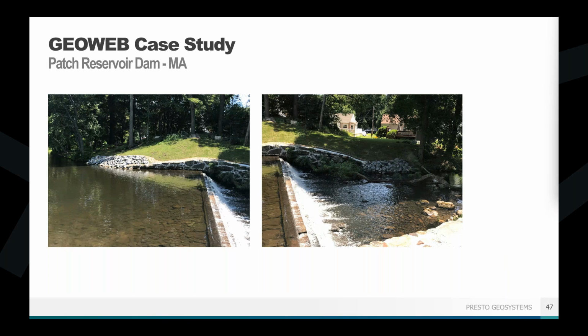So a solution had to be found to bring that dam spillway and the access road into compliance, as well as stabilize the embankment above the dam training walls. Potential conditions included design flood conditions, overtopping, and erosion control during both normal and flood operations. Additionally, the roadway needed to be upgraded to support heavier vehicles because initially, again, late 1800s, slightly different vehicles than what we're driving now. They wanted to make sure that roadway could actually support maintenance vehicles, potential emergency vehicles, anything like that.